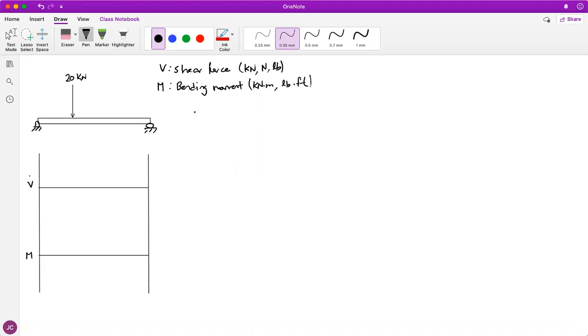Well, having said that, let me try to show you something. If you break apart the beam, what you want to find is the shear force, which is the tangential component of a force. We have already seen something called the axial force. It's along this length. This is called the axial force. We see this mechanical effect when we talk about tension or compression.